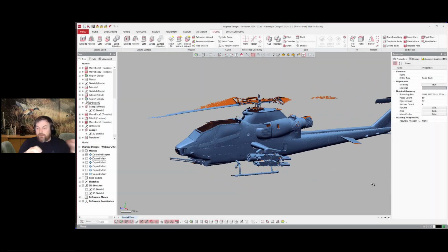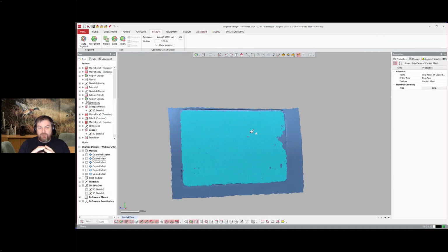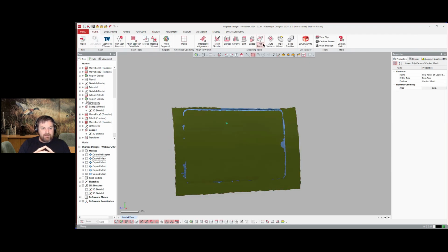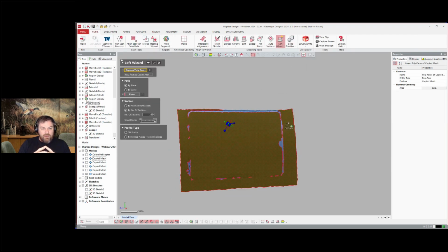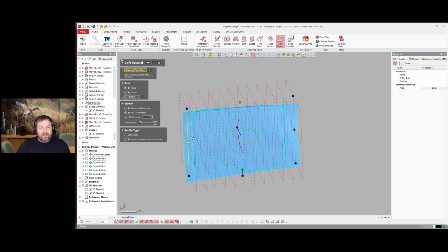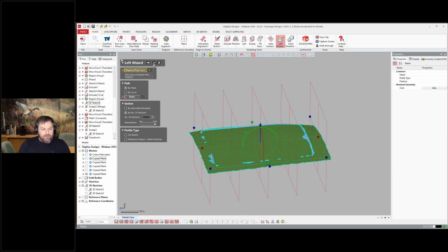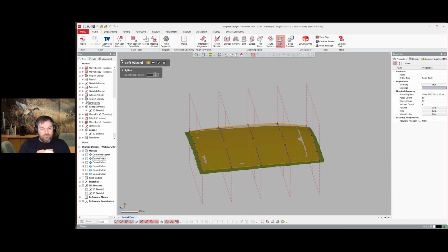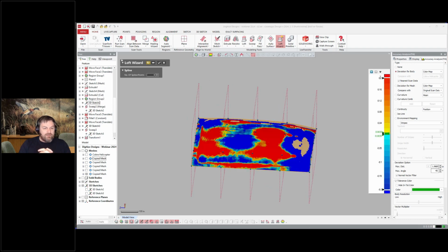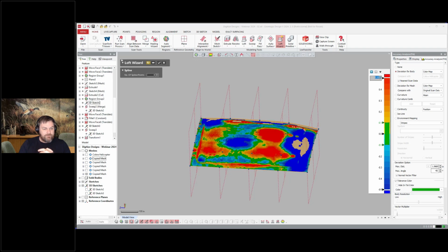So some of the other tools that are in here, we're basically doing a collection of lots of different things that would help within an application like this, where you have maintenance on these military vehicles. If I needed to recreate this door, whether I'm modeling the entire part or just this component here, you see I can create a region on that door panel, adjust the tolerances, and do a 3D compare and just see how closely I'm fitting to that mesh.